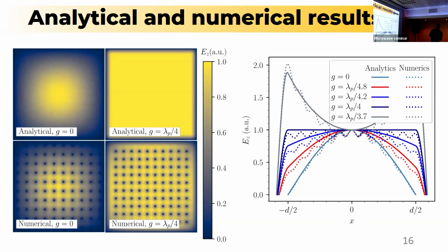So we start with the sinusoidal profile going to 0 at the edges. Then we go to the case of the uniform field in the wire media region when the G is equal to lambda over 4. And then when we overcome that value of lambda over 4, we start to get a behavior in which the electromagnetic field starts to be localized close to the cavity walls. This is the behavior of the gray curve in our chart.